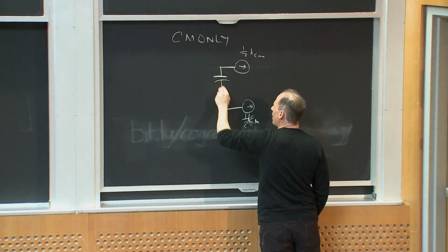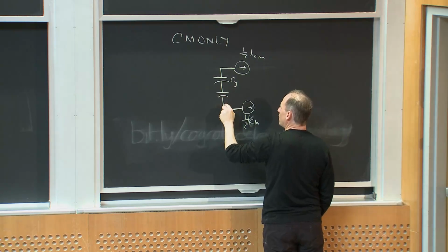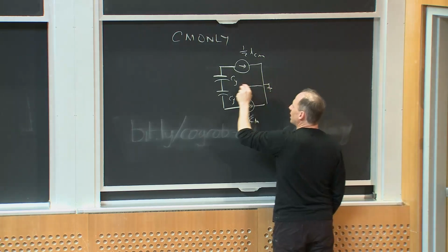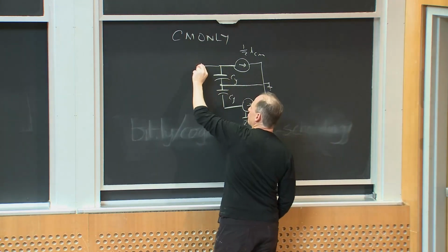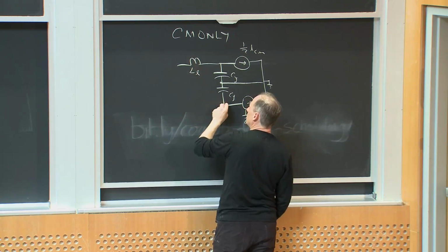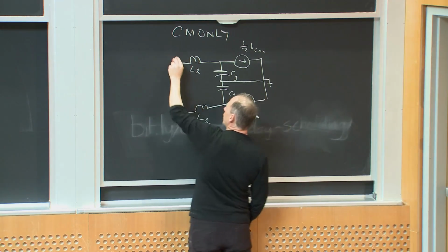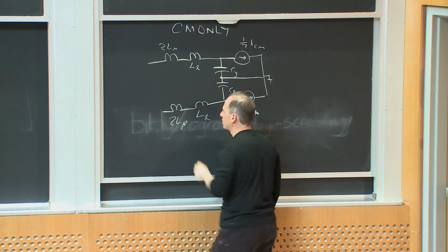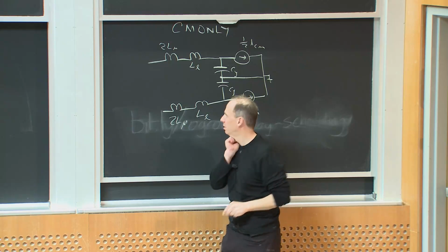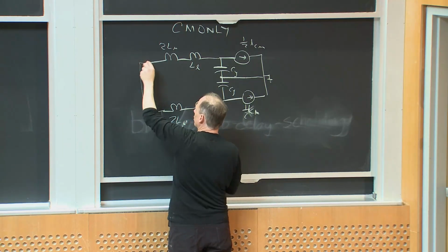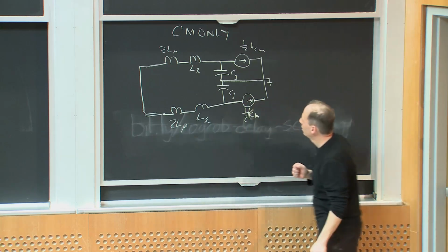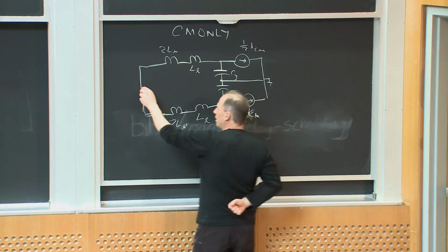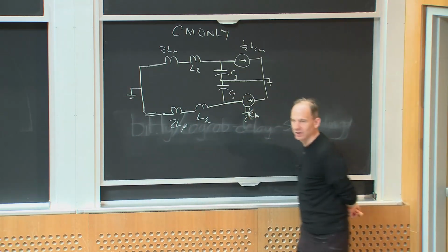Here I have CY, here I have CY, and then these are both going to ground, which is connected back here, okay. Then I'm going through L leakage on each side and 2L mu on each side. Right, because the ideal portion of the transformer is now gone, right? And then this is connected back to my input, which I'll just treat as a short circuit, okay? So the currents here basically form, and I'm acknowledging that I have ground connected back here too, right?